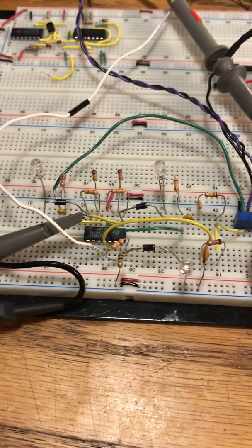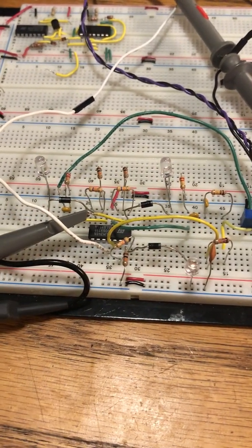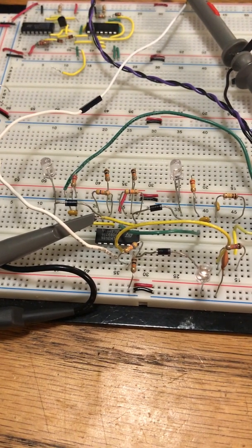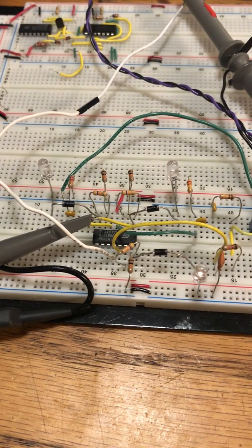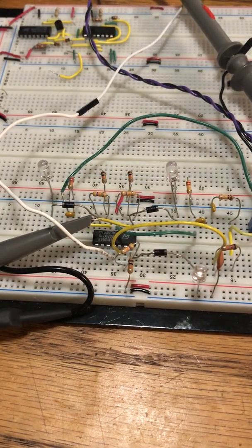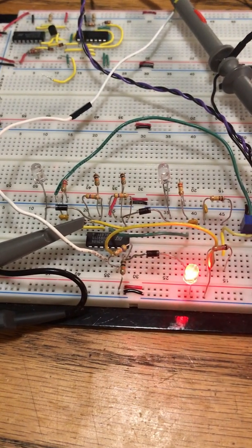So to demonstrate, I'll turn the network sweep on, and the network sweep is right now going from 50 hertz to 20 kilohertz, because we would want to go from 20 hertz, but it just gets really slow for the low frequencies, and this will illustrate it well. Once I turn it on, the low pass filter will turn on, then the band pass filter, then the high pass, and then it will repeat. Yeah, you actually see the lower frequency.